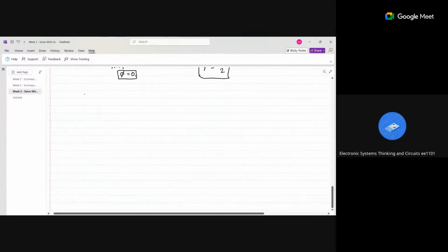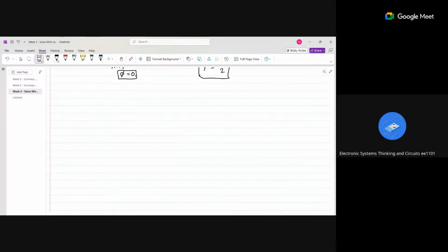In this lecture, we will be deriving the equation for a circuit like this. V of t is the AC voltage, and I of t is the AC current flowing through the resistor. For this, we first find the instantaneous power. What is instantaneous power? It is V of t times I of t at a particular time, the power at one point of time. It's not over a small amount of time.